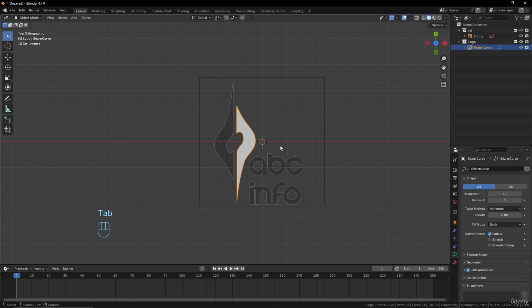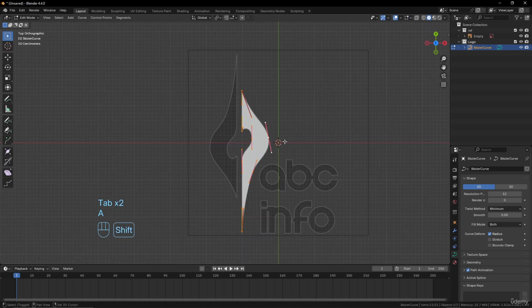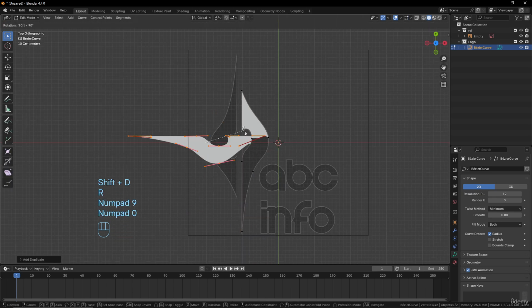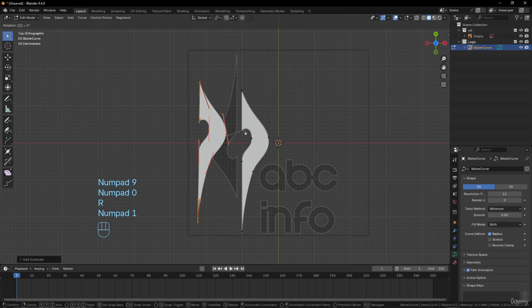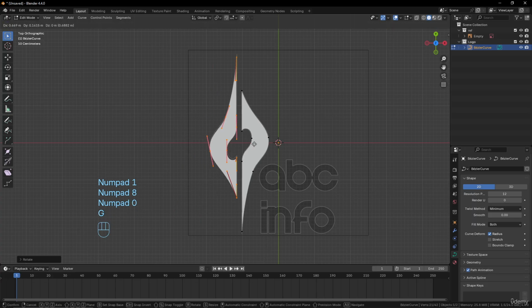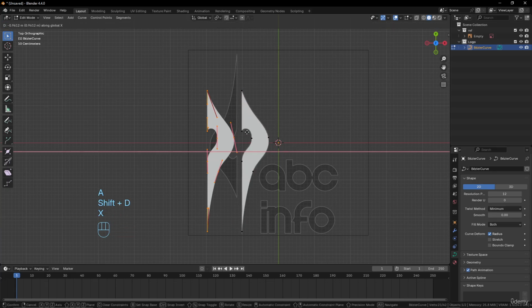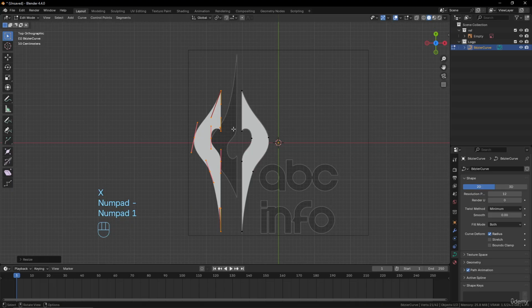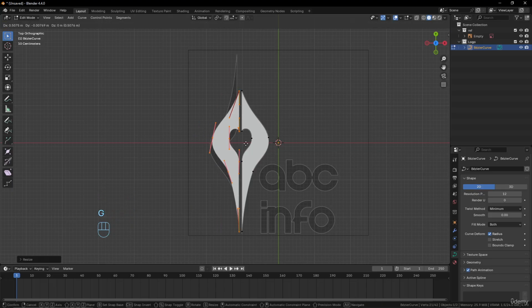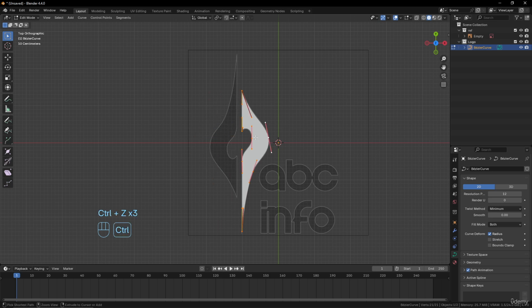Good. So what we will do, we'll just select everything, duplicate it, and make a rotation of 180 degrees, and put it back here. In case you want a mirror, for example, okay? So let's say you want to make the same, but with a mirror. You select everything, you make Shift D along the X-axis and make an SX -1. And like this, you will have the full mirror, okay? Very easy to manage. You can play with holes as well. So I will come back to that.